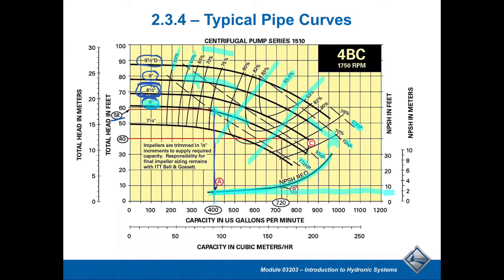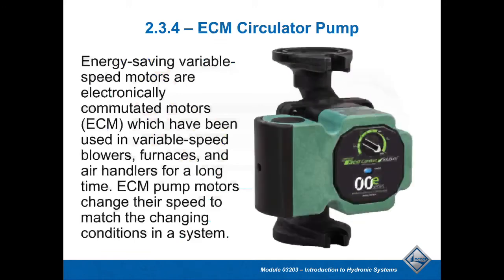So be sure to read through that section in your book on the pump curves and being able to read it. So all this, the essential parts of a pump curve is identifying our capacity in GPM. It identifies the amount of head that the pump creates as far as pressure, and that's what's going to be used to overcome those resistances. So in a circulating pump, those are the two most important parts of that circulating rating system that allows us to determine our flow in a system.